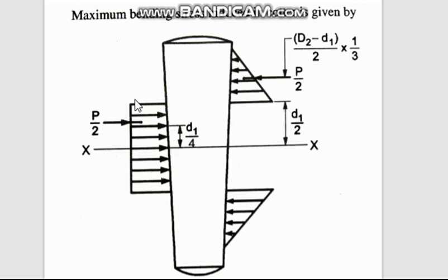Okay, so the total load that is being pulled is P. See, this Cotter is straight on one side and tapered on one side. And we are pulling with load P. If you consider only half of this, that means up to above the line XX, in the center P by 2 will be applied, and here another P by 2, totally P. Similarly, when the socket collar is pulling that side, P by 2 will be applied here.